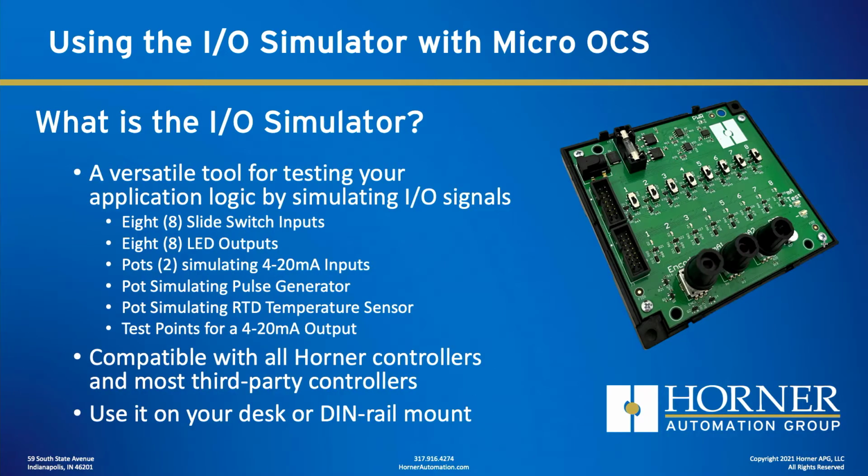What is the I/O simulator? Well, this is really a versatile tool for testing your application logic by simulating I/O signals on your desk or in the lab. The I/O simulator has 8 slide switch inputs, 8 LED outputs. It has 2 pots that can be used to simulate 4 to 20 milliamp sensors. It has a pot that simulates an encoder. It has another pot that simulates an RTD temperature sensor, and it has a couple of test clip points for measuring the 4 to 20 milliamp output from the OCS.